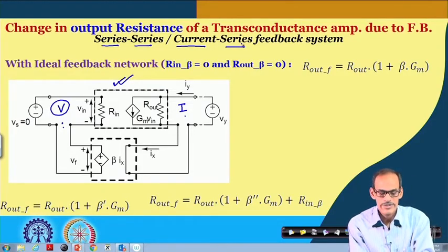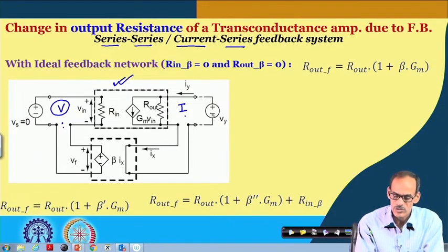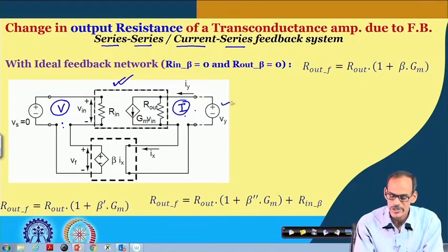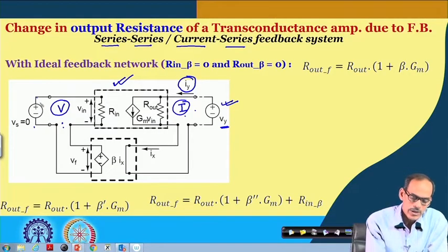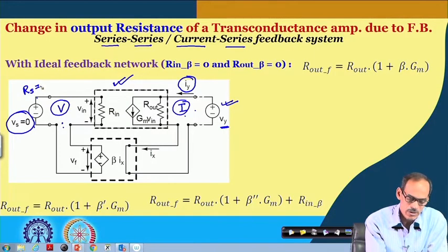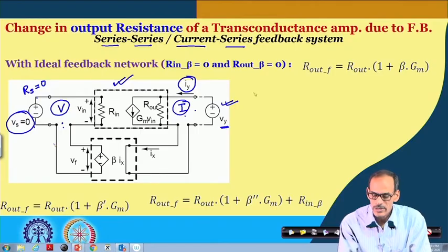Here also it will be very similar to our previous discussion. As we said, to get the output resistance, we need to stimulate this circuit by one voltage source, and then we can observe the corresponding current here, keeping the input port condition supporting the feedback network. Namely, we are keeping the source signal at 0, and for the ideal condition to start with, we are considering the source Thevenin equivalent source resistance equals 0. So, from that we can say V in equals minus V f.